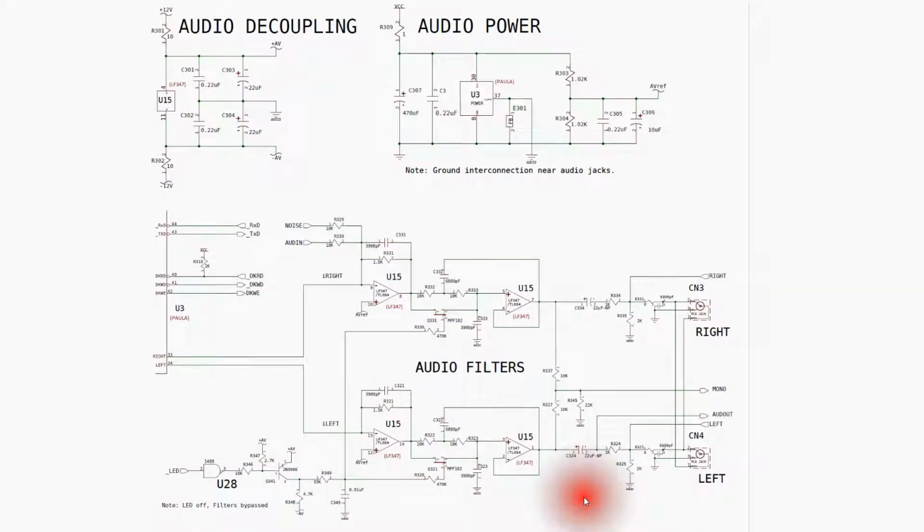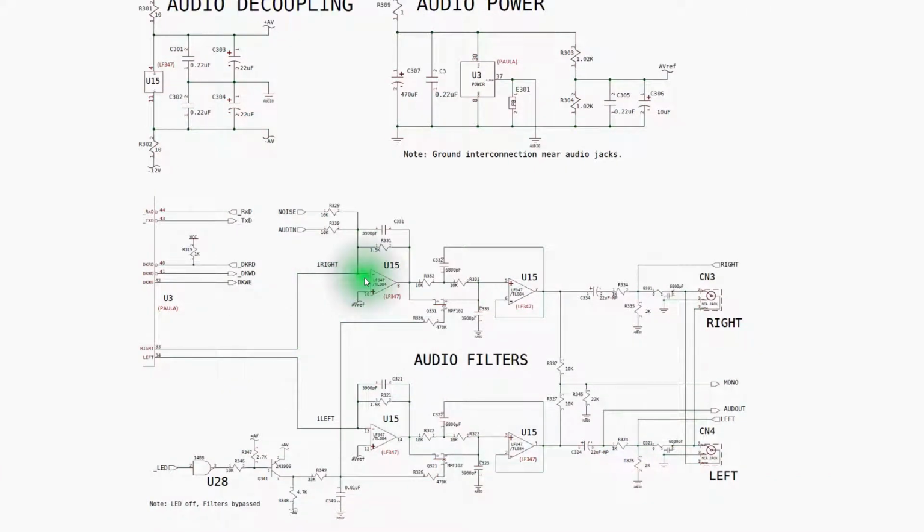So back in the schematic, I've labeled this audio in, buffered audio out to what I'm calling buffered audio in, to drive audio out to the DC blocking capacitor here, and to the connector. This capacitor exists here to block DC voltages from getting through. AC will pass through a capacitor, so the sound, because it's an AC voltage, will pass through the cap, while the DC voltages generated here are blocked. So it keeps you from taking the raw voltage coming on the output of this op amp and feeding it all the way through. Only the audio or AC portion makes it through.